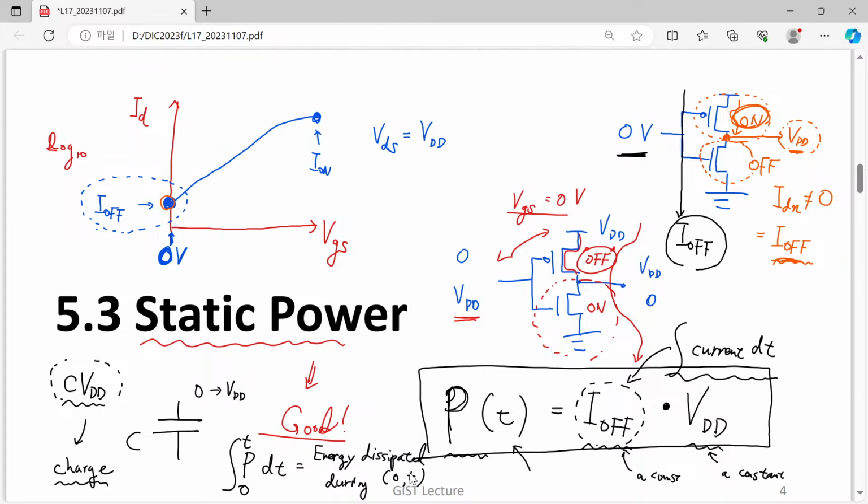So then we can make a comparison between this switching power consumption and static power consumption. The reason why we call it static power consumption is, although we do not switch our transistors or our logic gate, it is always there. It means that even though we do not process our signal, our information, power is still spent in this time.